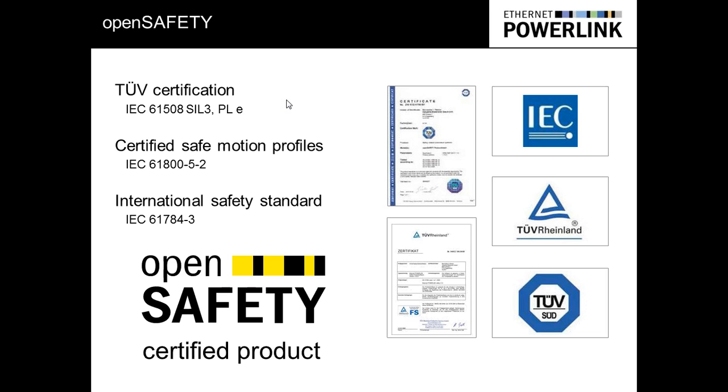Okay, so I mentioned in the second video that I showed that there is some safety communication going on. Generally people think of safety as a hardwired solution. So if I want to have an emergency stop button, or a light curtain, or any other safety features, I typically will hardwire things. Well, you can actually have safety sitting on POWERLINK instead. If I want to add the safe component, all I need to do is put it on the same POWERLINK network, and POWERLINK speaks safety.